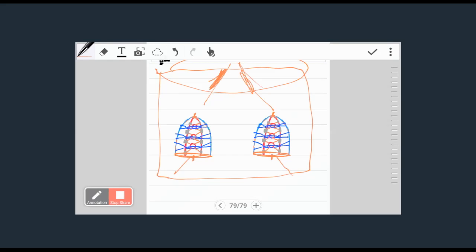And remember one thing. These connections that you are making, always make them from the same wire. I said the coil connections that you are making, try to make them from the same gauge of the wire. Don't put a thinner wire for the connection.